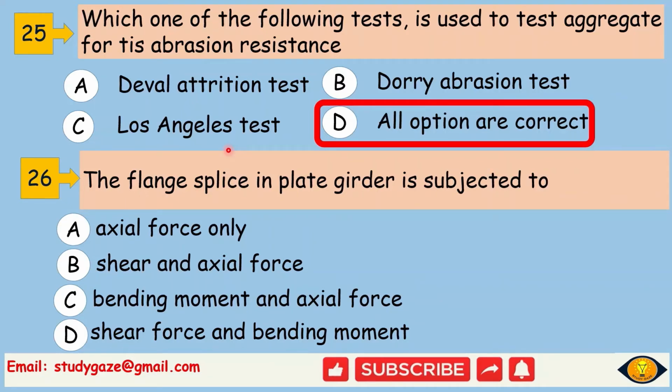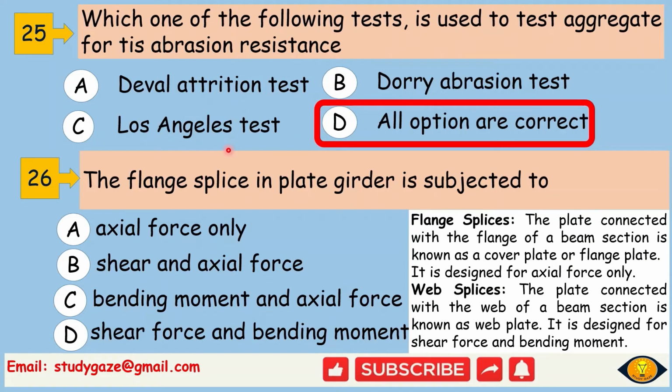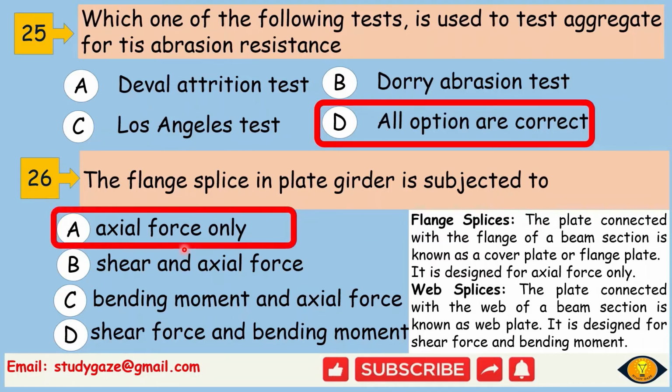The correct option is: flange splice is the plate connected with the flange of a beam section, known as a cover plate or flange plate. It is designed for axial force only. So the correct option is A, axial force only. If it was a web splice, the plate connected with the web of a beam section is known as a web plate. It is designed for shear force and bending moment. But here they have asked about the flange splice, so the correct option is A, that is axial force only.